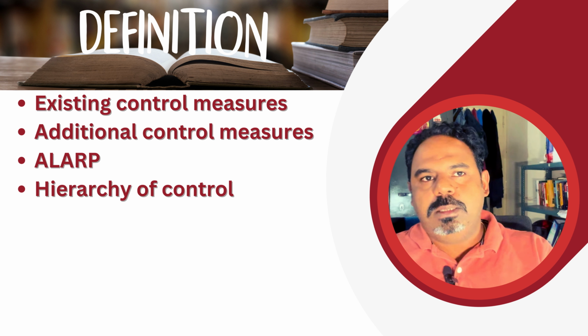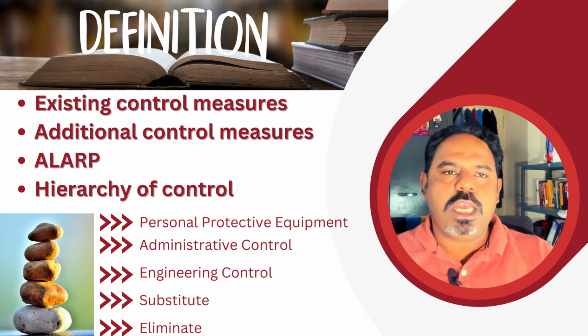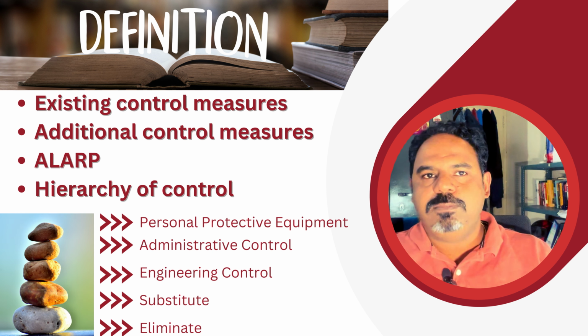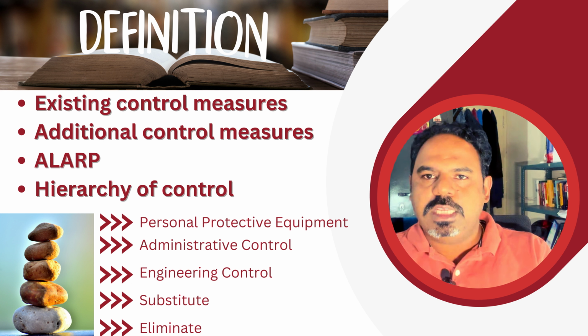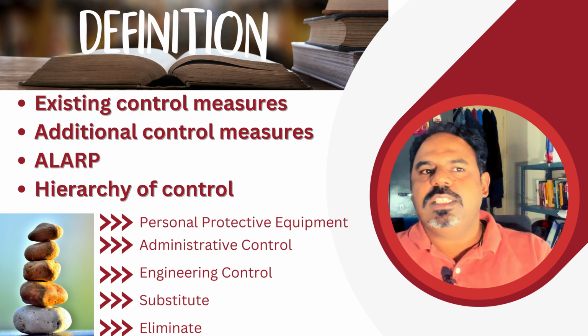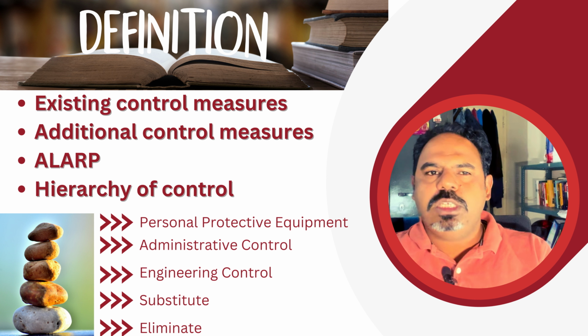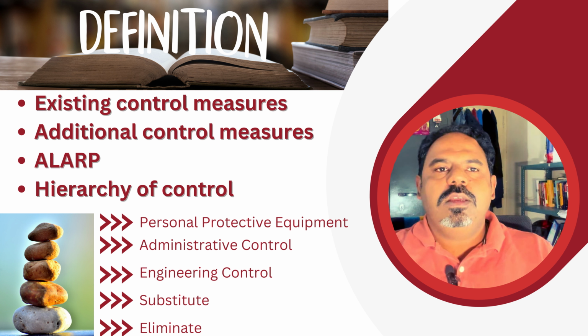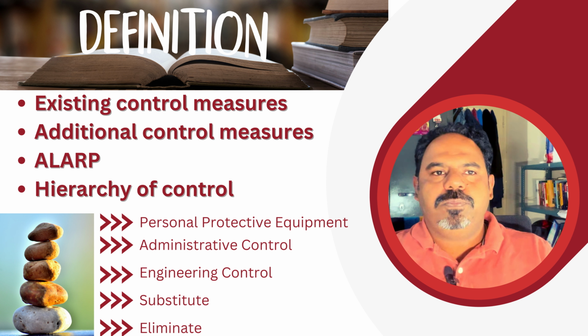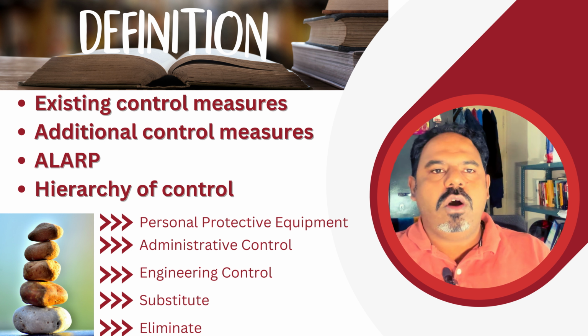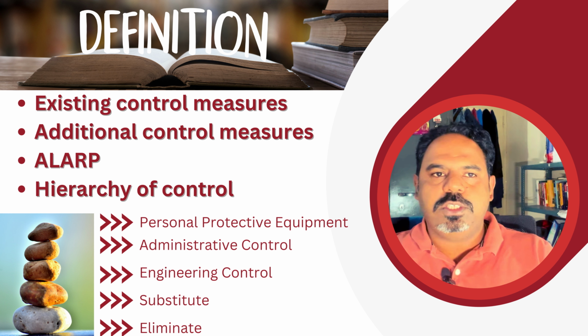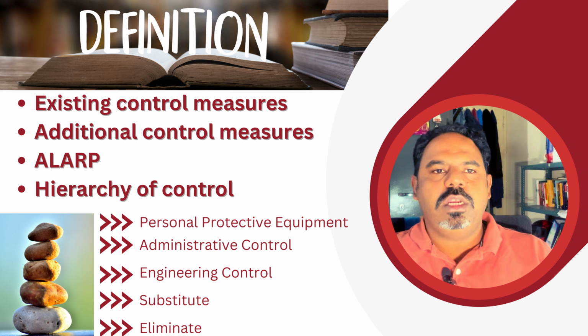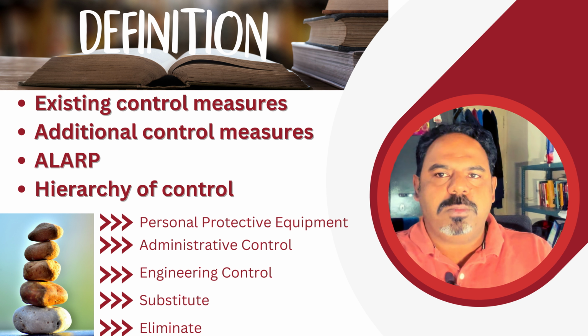Below are the best way to propose it, which are elimination of hazard. As the name suggests, here we are trying to eliminate the hazard altogether. However, this is a difficult task in practice and mostly has a very small window in the entire project time frame where we can apply such control measures. But the effect of such control measures will result in complete removal of a particular hazard type from the construction sites. The scope of such implementation is also mostly limited to design phase of a construction project.